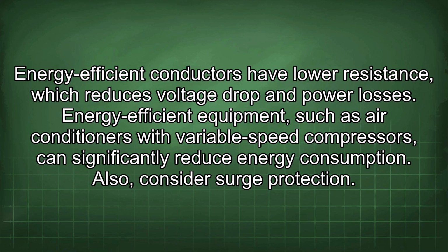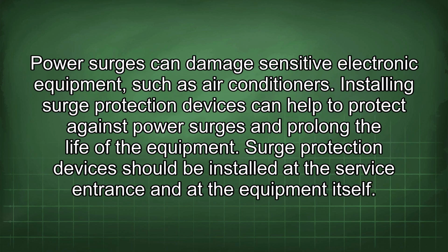Also, consider surge protection. Power surges can damage sensitive electronic equipment, such as air conditioners. Installing surge protection devices can help to protect against power surges and prolong the life of the equipment. Surge protection devices should be installed at the service entrance and at the equipment itself.